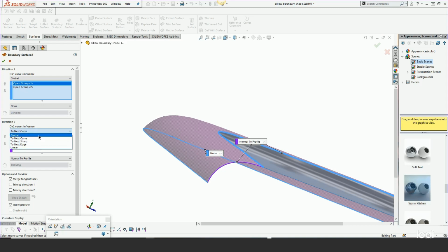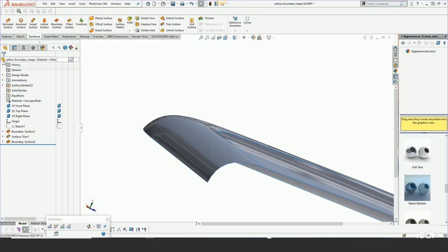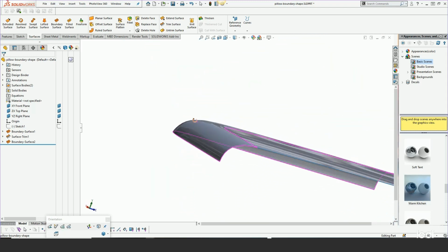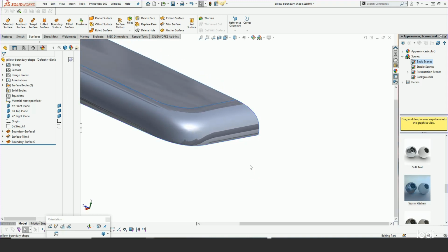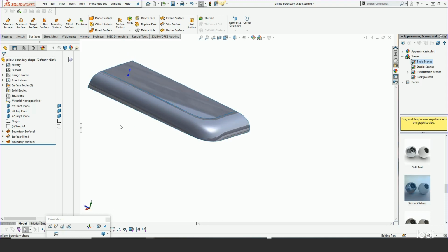And that's what this feature is good for, if you're building boundaries and it's wrapping around corners and you want that corner to fill out just a bit more, this is a good option for that by using next curve, which you can see there fills it out. Okay, and then sometimes you get just a little too much influence on the boundary here. We'll take a look at that with some zebra and see what we get. But at this point, we've got everything that we need.